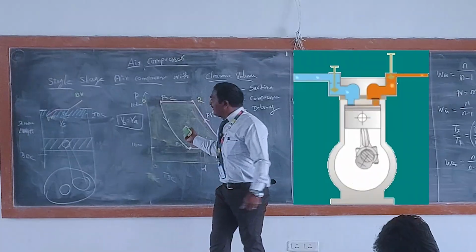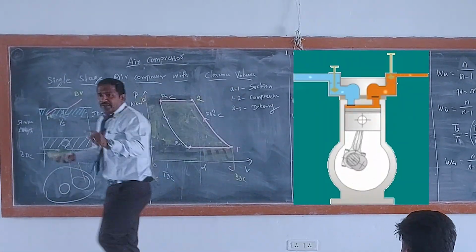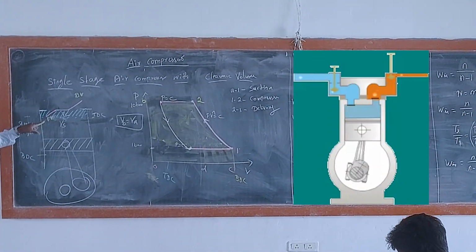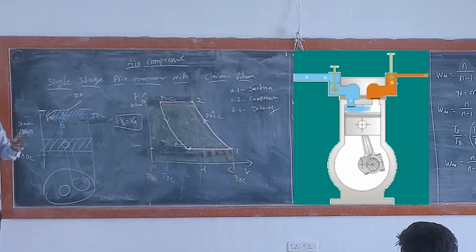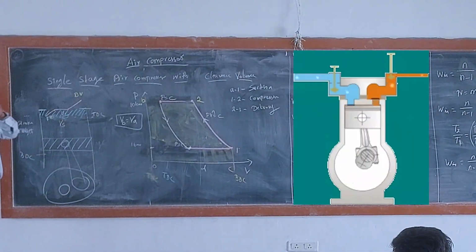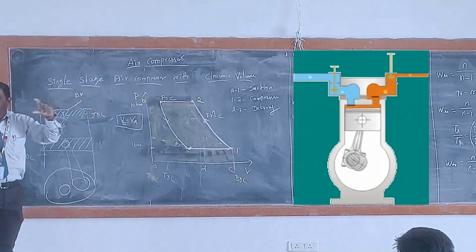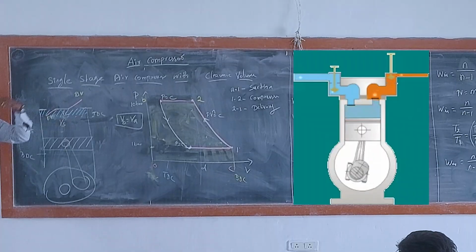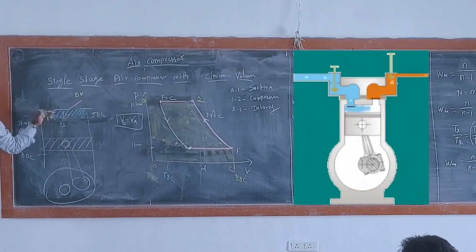So these are the differences between with clearance volume and without clearance volume. In delivery, do you need a large quantity of air or a small quantity of air? I'll tell you two things. One thing, the delivery air is reduced due to clearance volume. The other thing, to expand this gas, we have to give work to the system. Again, we are expanding this gas, right?